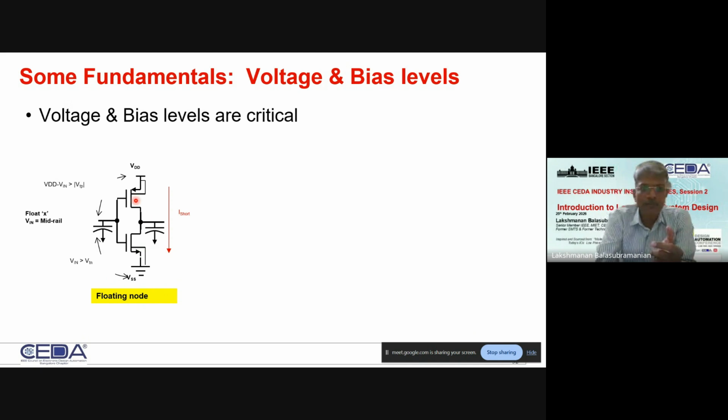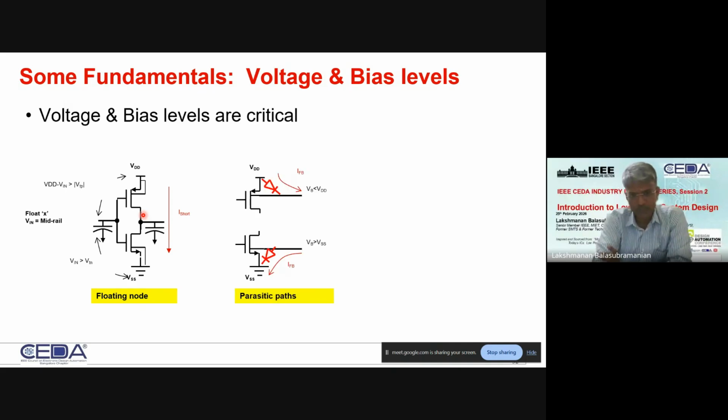For example, just to give you an idea, if the dynamic current consumption of this inverter for given capacitors and the voltage supply is about, say, 10 milliamps, peak current, but average current, I've not shown the waveform here, of just a few milliamps or few microamps, the short current can be 2 or 3 orders of magnitude higher than the normal operating dynamic average current, right? I'm not talking about the peak dynamic current, I'm talking about the average activity here.